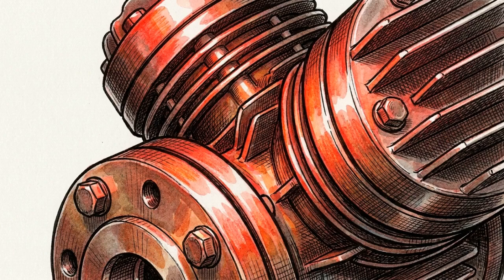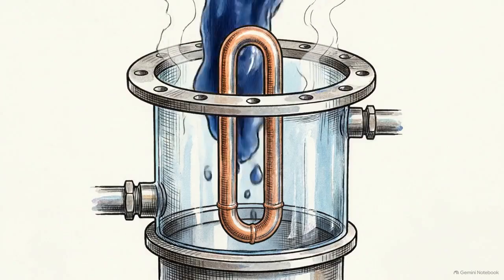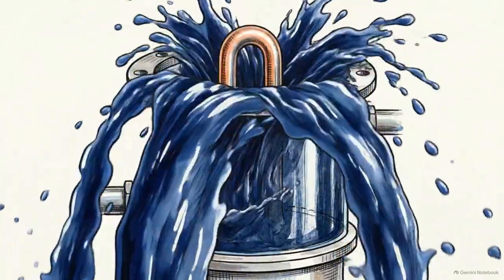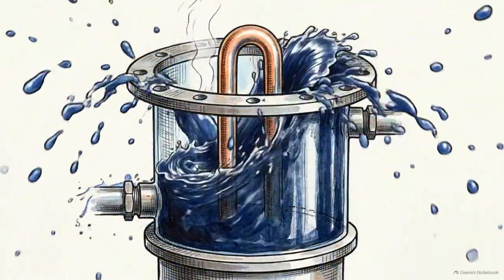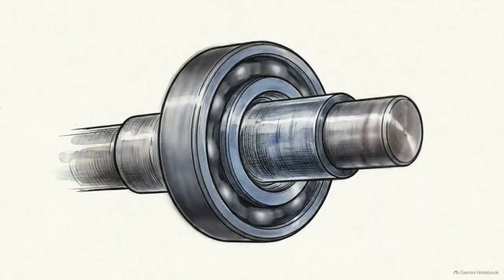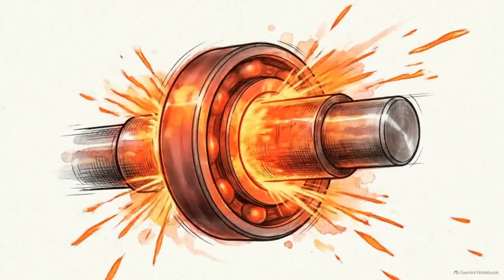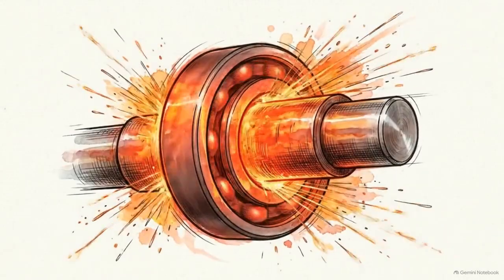When an accumulator fails, the protection for the entire system is compromised. If the vessel is undersized, it can overflow during a severe floodback event, allowing liquid to enter the compressor unimpeded. If debris clogs the metering orifice, oil return stops. This leads to increased friction, heat, and eventual seizure of the compressor.